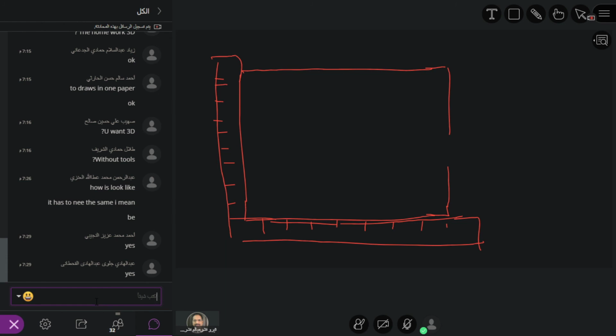So if you want to use the template, then mark this point and draw these two lines. Okay, then your template is like this. When you buy the template, it will be somewhere here. So this is, let's say, 5 mm diameter. So in the template there will be two lines given like this. So bring the template here and make these lines coincide with these two lines, so that automatically it makes the center, and put the pencil here and make the circle. You follow me?